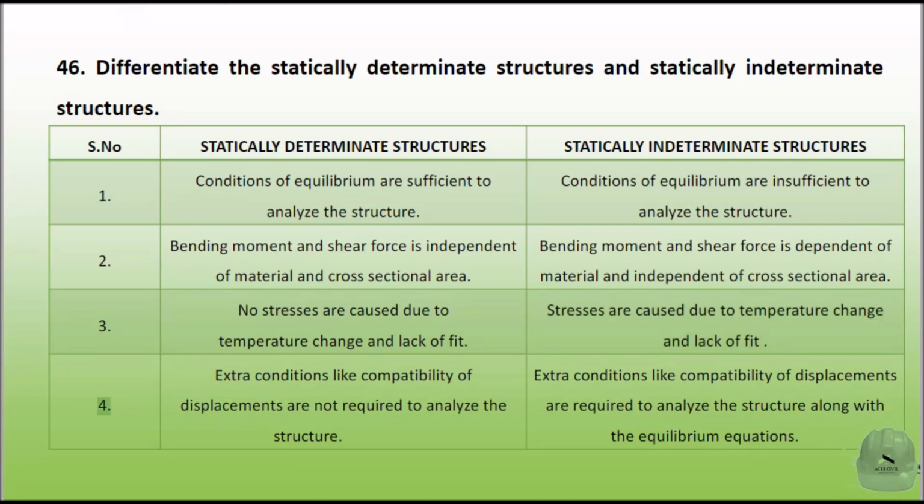4. For determinate structures, extra conditions like compatibility of displacements are not required to analyze the structure. For indeterminate structures, extra conditions like compatibility of displacements are required to analyze the structure along with the equilibrium equations.